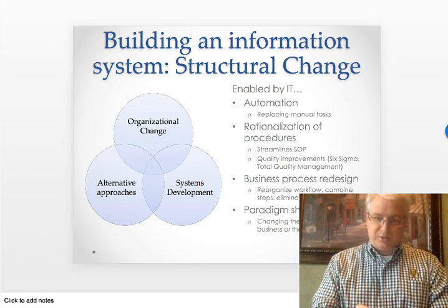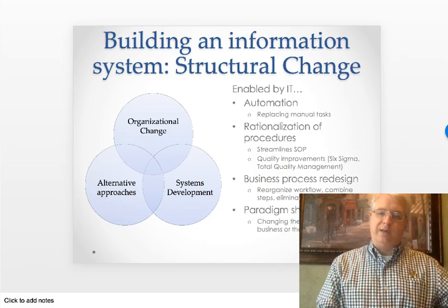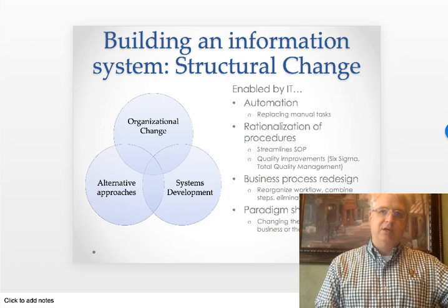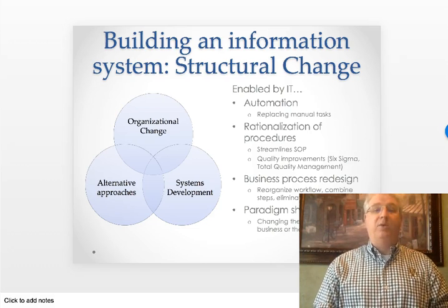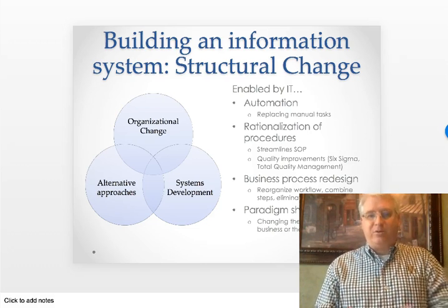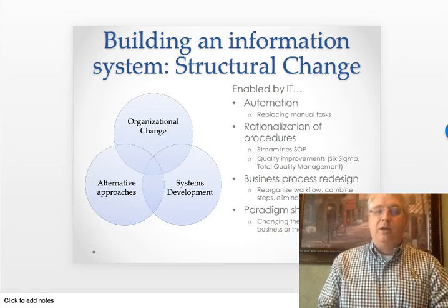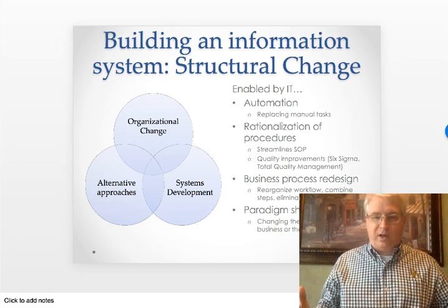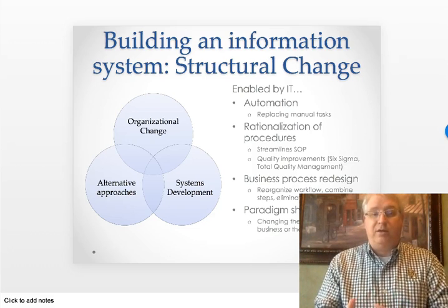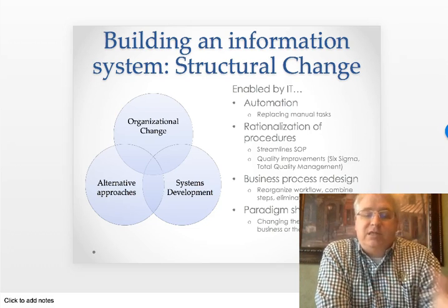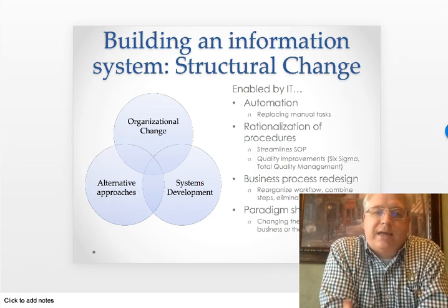Well, a lean approach to that process is going to ask, why is the part 3 steps away? Because in total, that requires 6 steps. Well, you might think, okay, that's just going to take 1 or 2 seconds. Well, that's true. It will only take 1 or 2 seconds. But if you lean out that 1 or 2 seconds and make it half a second to grab the part and place it on, over time, over a number of people and over a number of facilities, you can actually increase the quality as well as the total time, turn time is what it's called, how fast you can turn a product out.